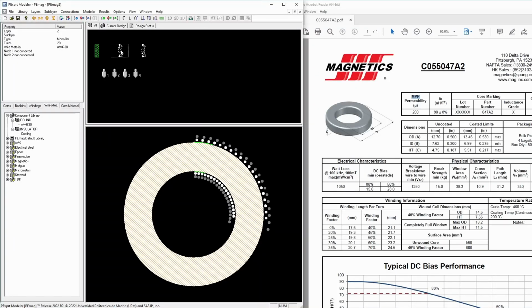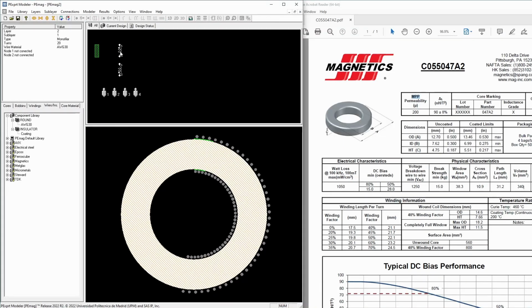So this one here is the first layer inside, and this one's the one outside. So if you want to get them on the same layer, you have to make this one a sublayer. So go up here to, let's see, one of these moving things, move selected sublayers. So we're going to move this one here, and now they're all lined up together. So that's taking up about half of it.